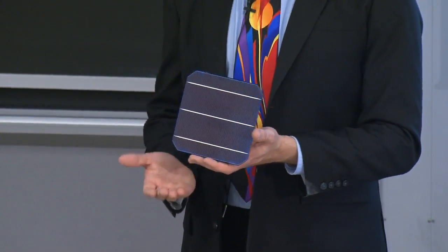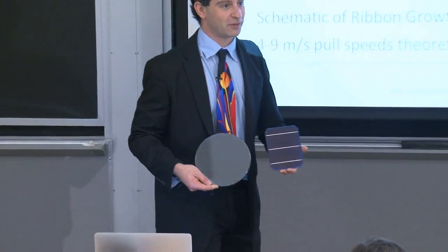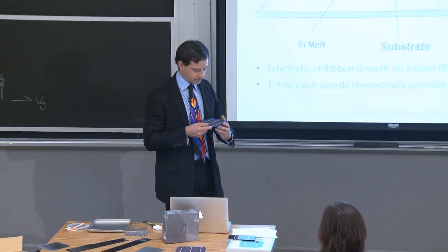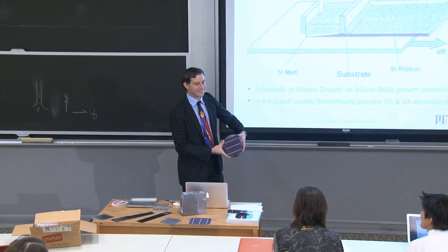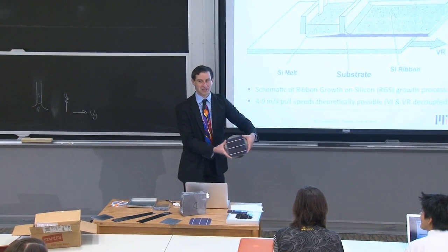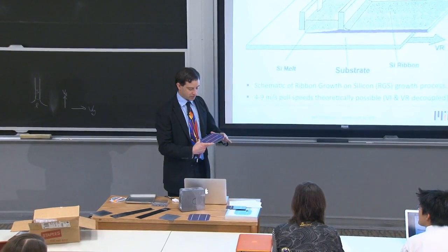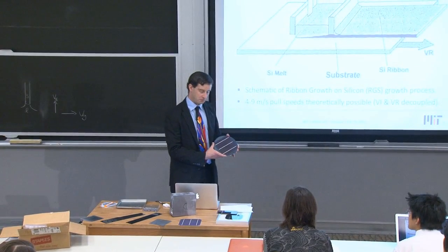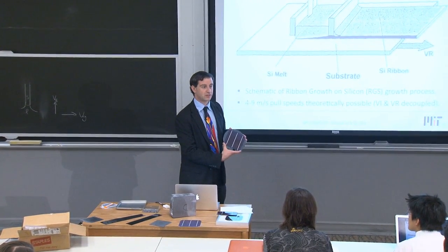You can see the edges are kind of rounded off. And that's because it came from a CZ wafer like this one. It was just chopped out of it. Let me see if these two are actually coincident. Oh yeah, look at that. So you can see where the solar cell actually came from. Okay. So that's the standard diameter, or let's say linear dimension, usually a rectilinear shape, a square. And the multicrystalline silicon ingot material is typically of this size as well.